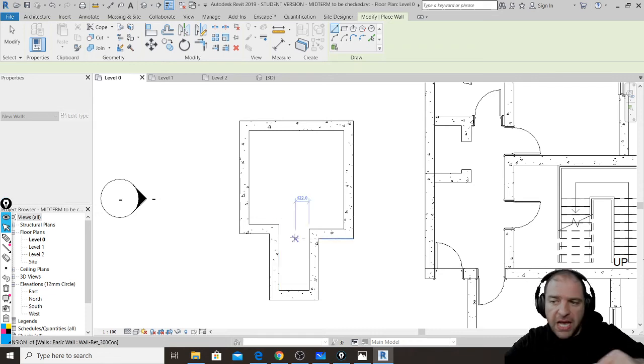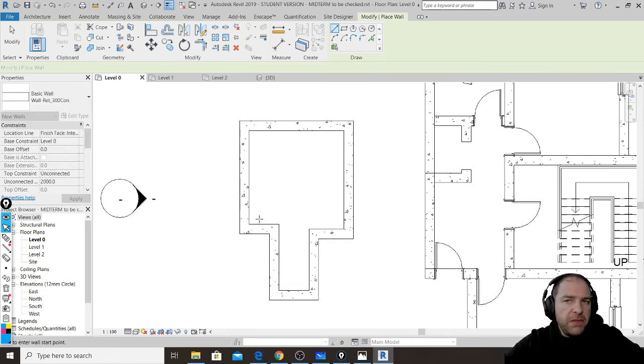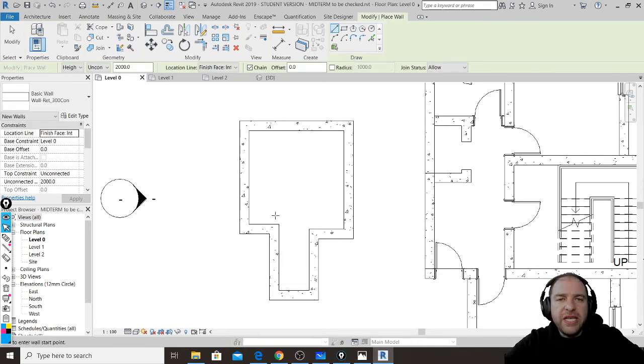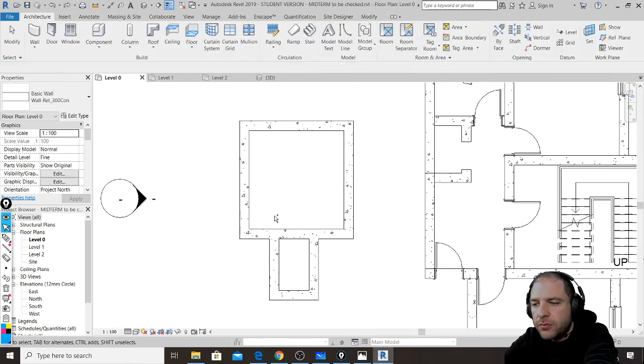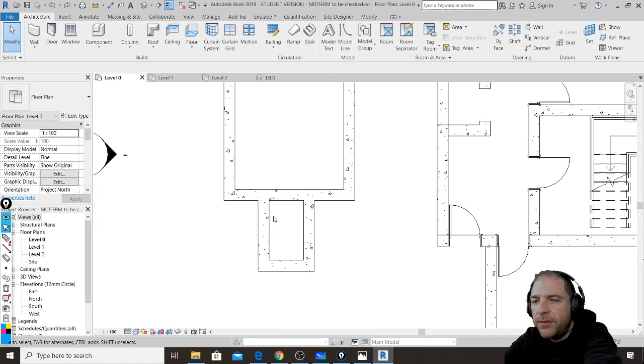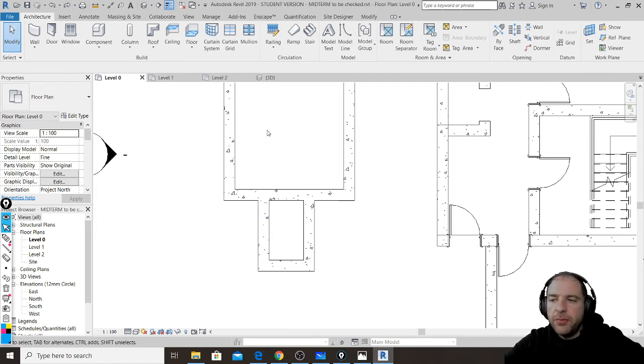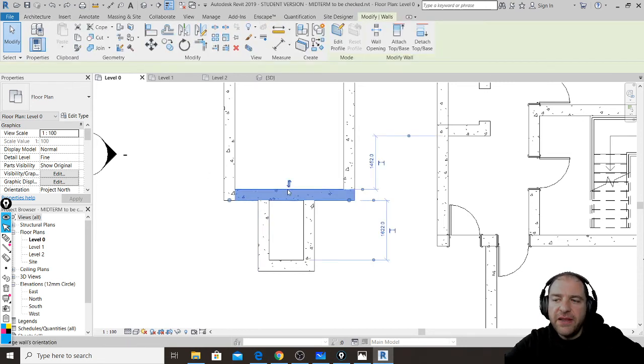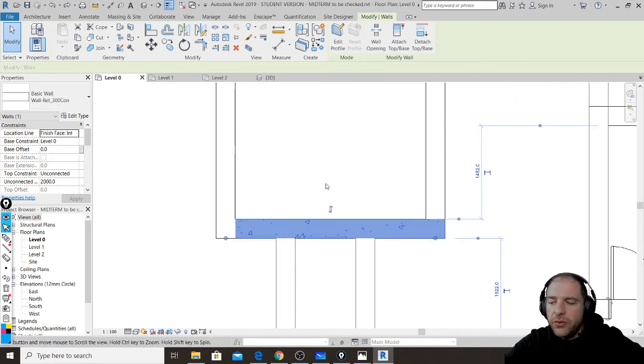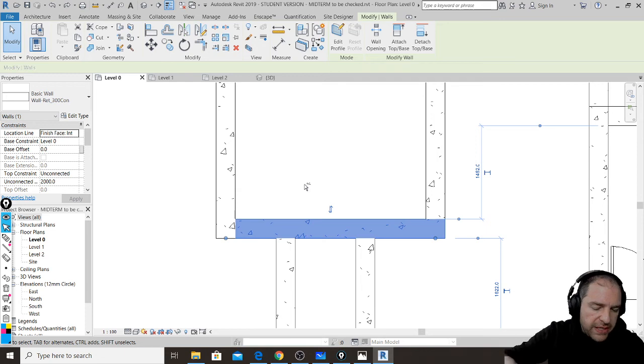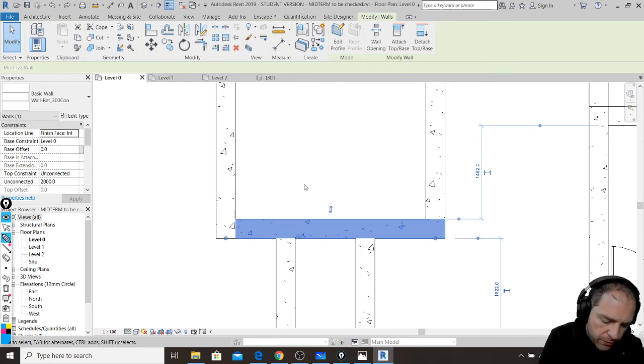So I have also made this mistake in here, so this will take forever. While this is not true, because in Revit there is this simple tool. You select the object, and in this object what I would like to do is just make a sketch.